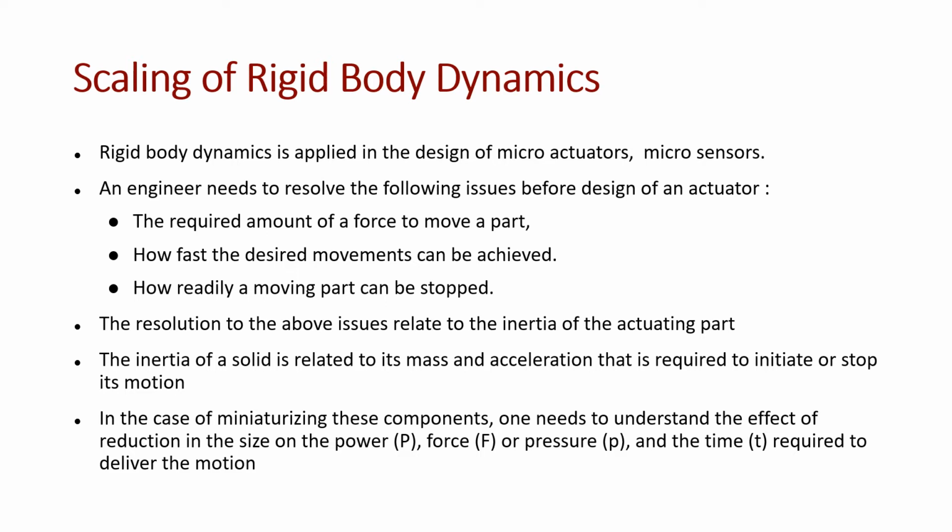All these issues relate to the physical parameter called inertia of the actuating part. And the inertia of a solid is related to its mass and the acceleration that is required to initiate or stop the motion of the solid. So when trying to miniaturize these components, one needs to understand the effect of reduction in size on the power, force, pressure, and the time required to deliver the motion.